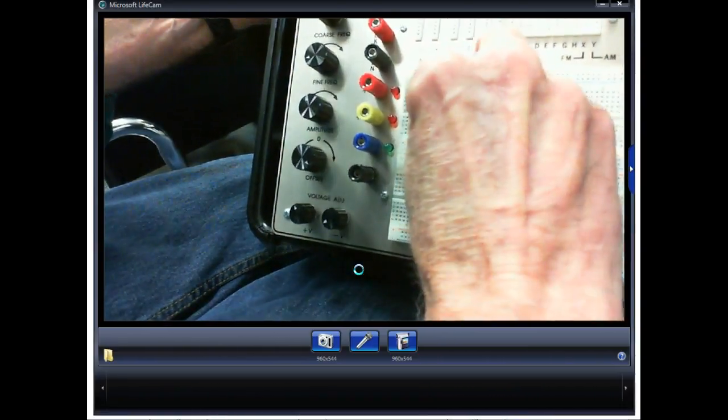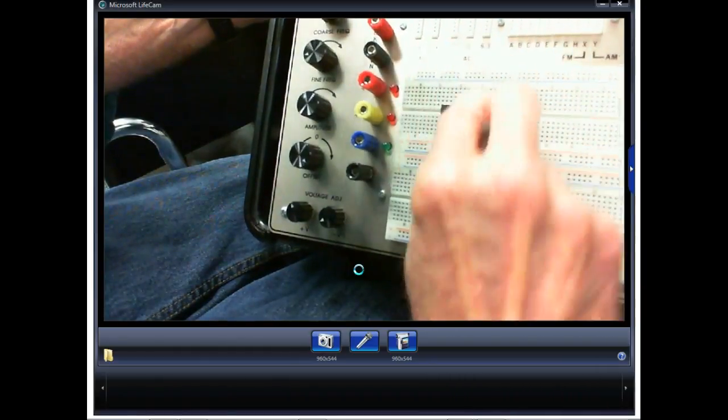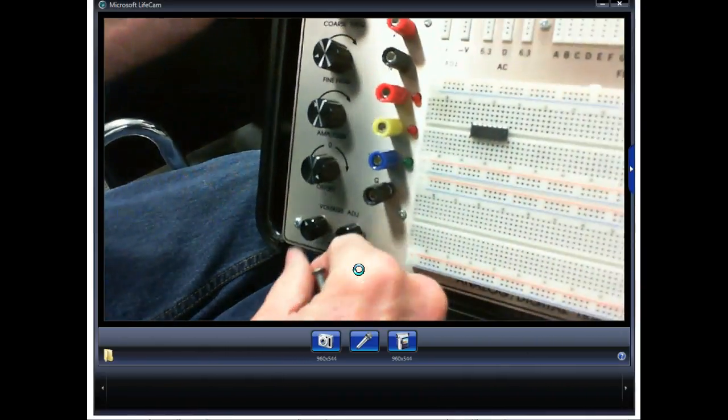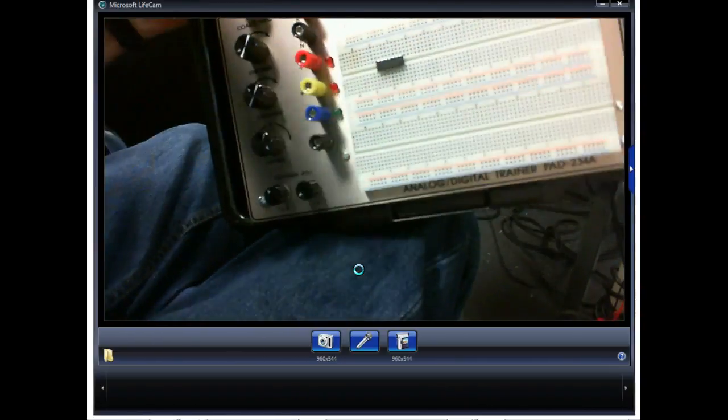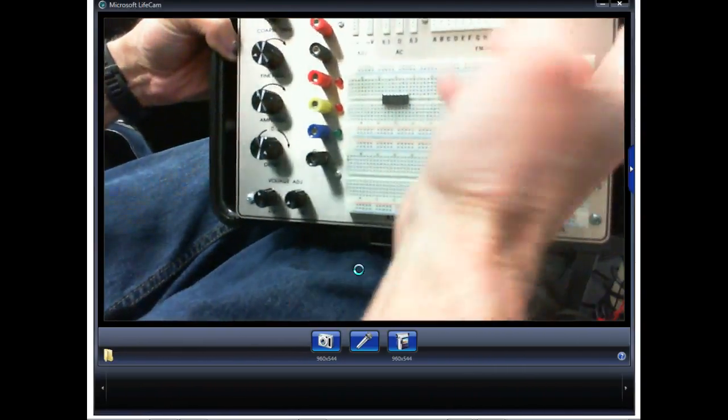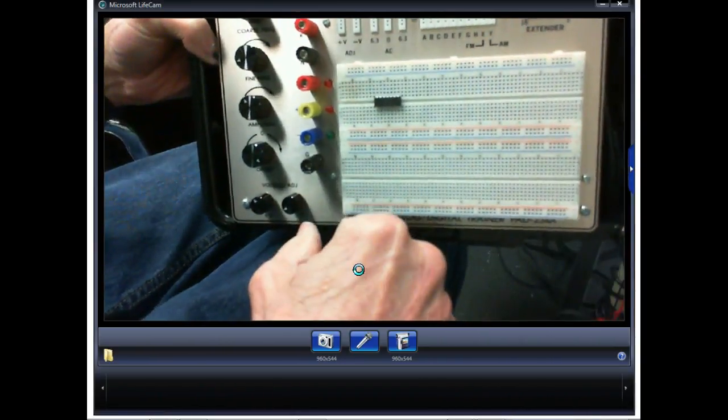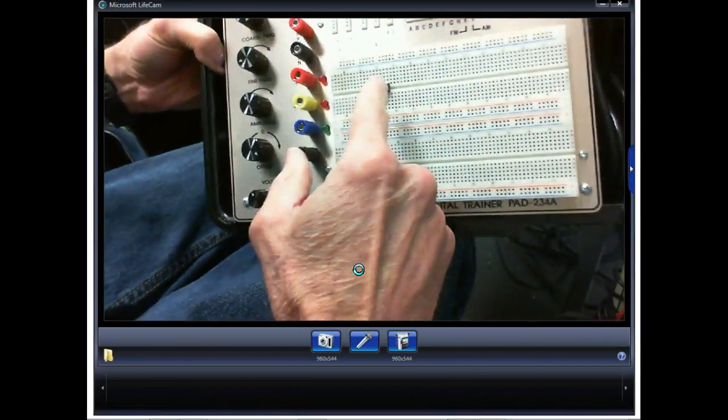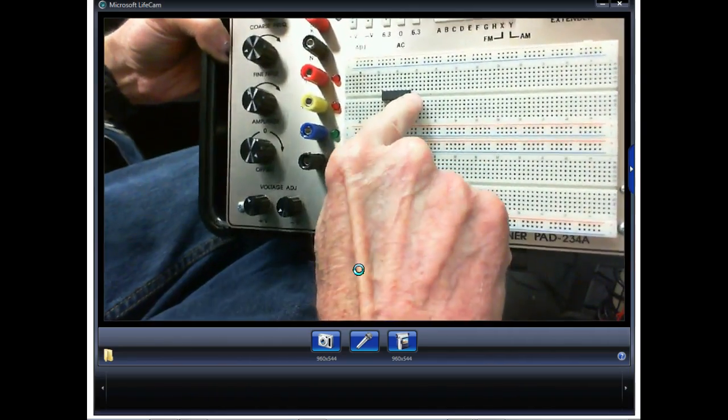Make sure you know where pin 1 is when you start wiring these things up. We're going to show y'all some. Make sure you know where pin 1's at. We get people that just come in here and they start wiring. They just hook the stuff up to a pin. Well, on these, that's where the notch is at.